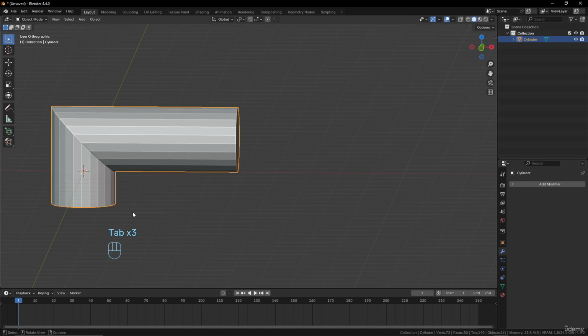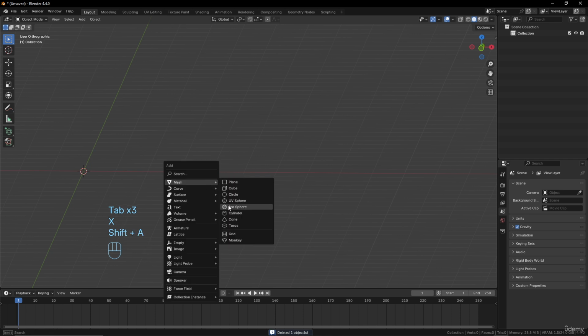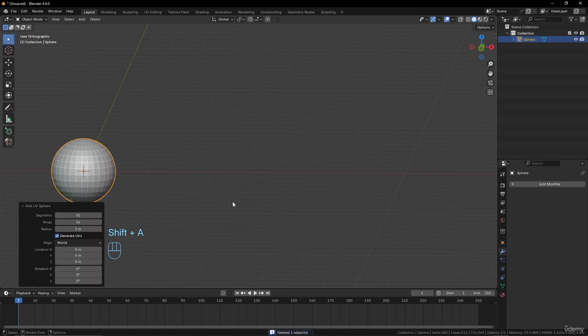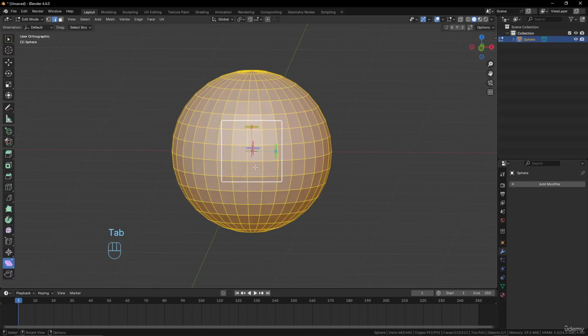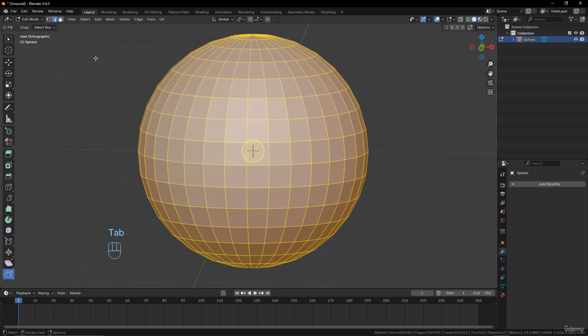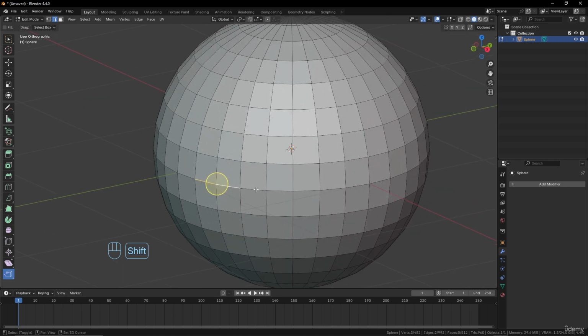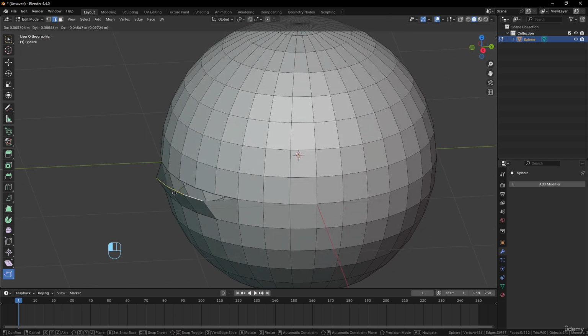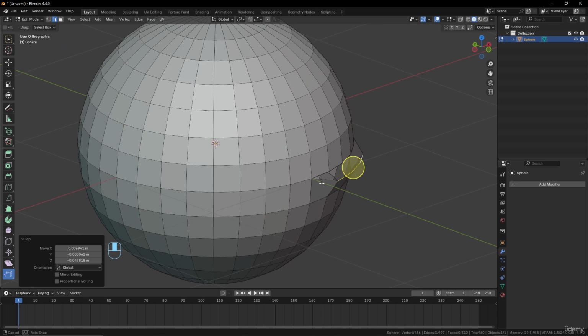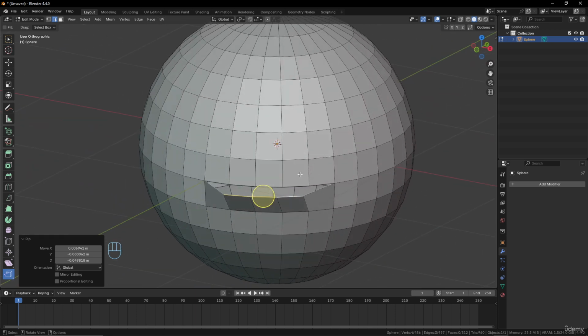And the last one, finally, is easy to understand, that one with the UV sphere. Okay, you just select a part somewhere and then you can just open the geometry. So be careful because it often creates triangles, and if you want to fill it back here, it will be with triangles, I guess. Or strange geometry anyway.